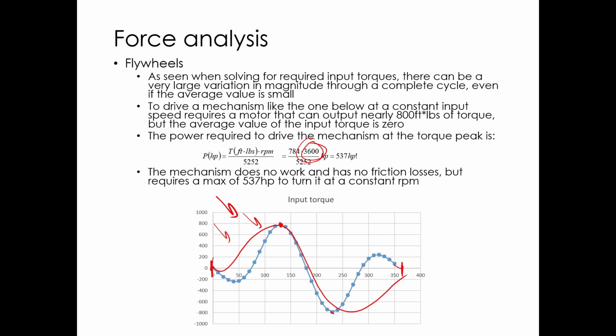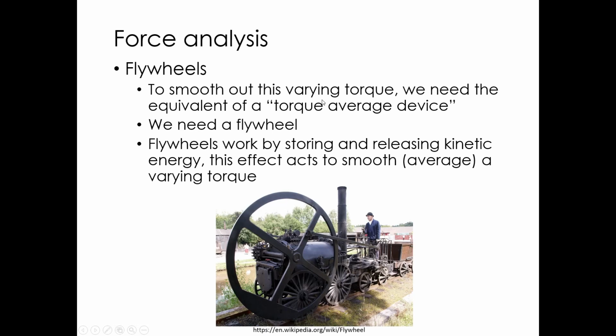So in this case, this engine, there's a 60 hertz torque ripple and speed ripple on the crank. So what we want to do is squish this down and make it better and reduce those vibrations and that torque and speed ripple. So that's really what we're doing with flywheels, is we're squishing this required input torque graph down, or making it run smoother. And you see this on all sorts of engines, especially big single-cylinder engines.